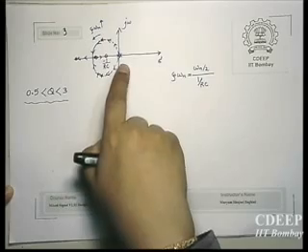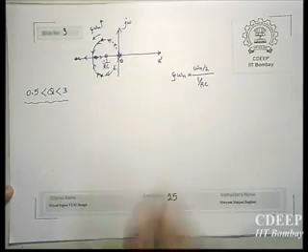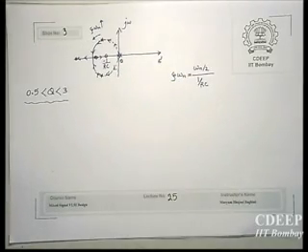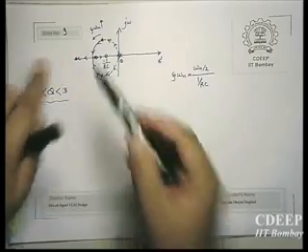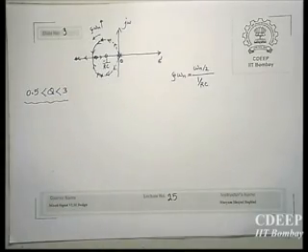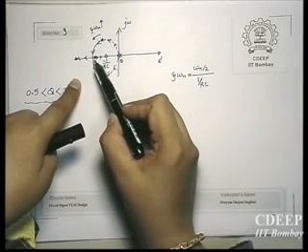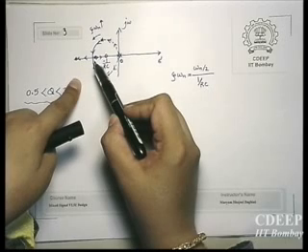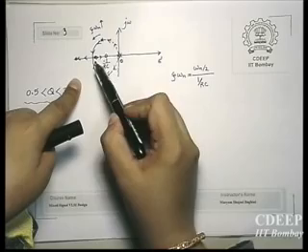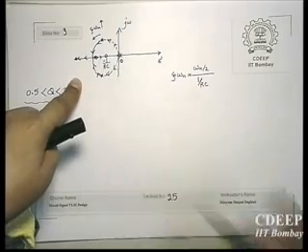The value which is closer is always the dominant pole, which has minimum magnitude. See, these are far from each other. Therefore, this pole is dominant. And this bandwidth becomes closer and closer.